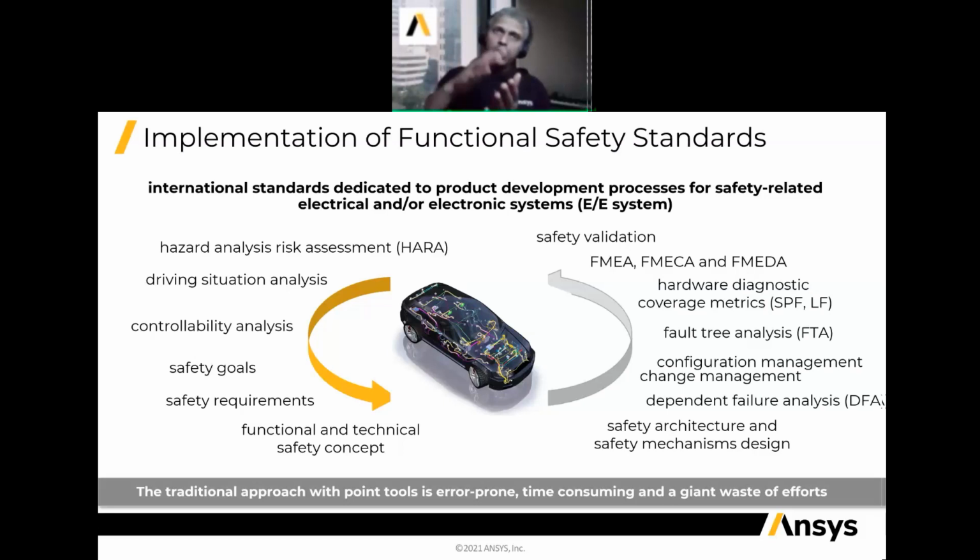And then it goes to level A, where certain additional requirements are imposed by ISO 26262, which incrementally goes up to level B, C, and finally up to D, which happens to be for the most safety critical functionalities of the vehicle. At each incremental level, the amount of activities that we need to perform increases, and at the same time the associated metrics become more and more stringent, all the way up to ASIL D, which is the highest level of our safety ASIL rating.